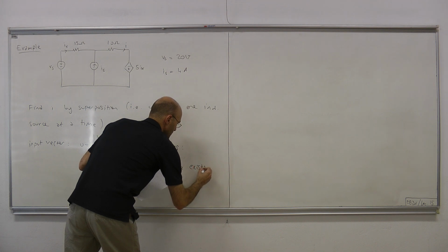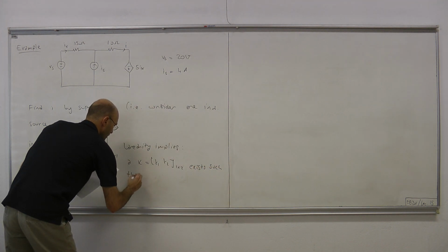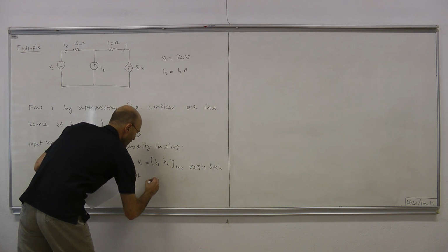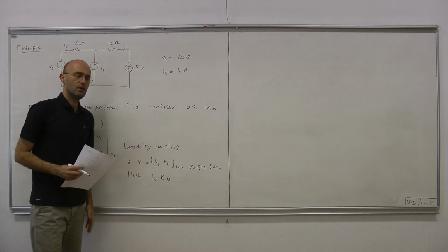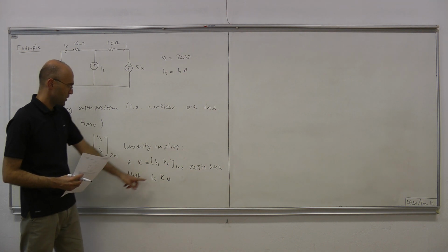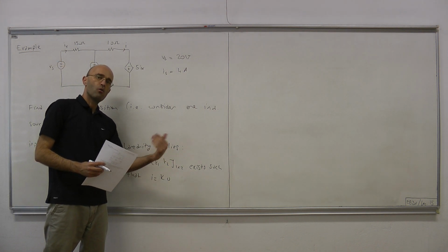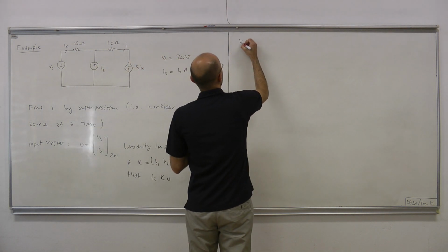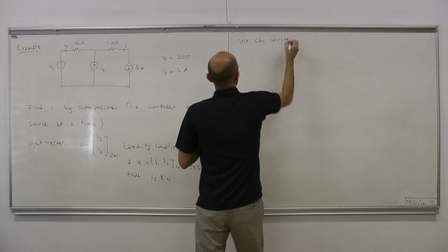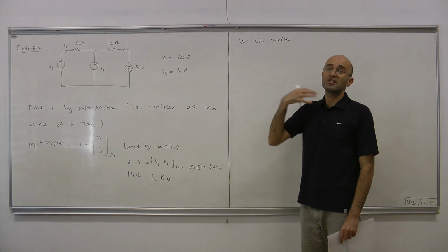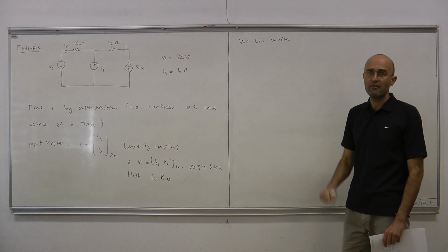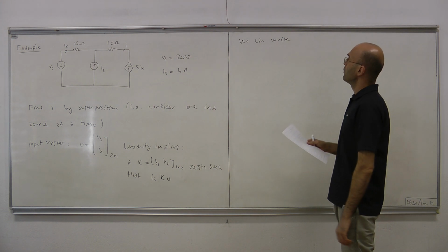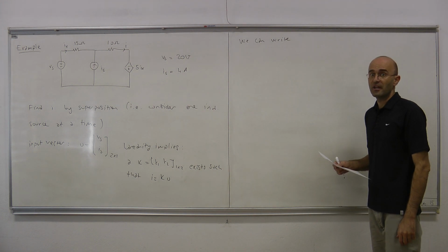It exists, and these K1 and K2 depend on the circuit topology and the parameters, of course, such that the output equals K times u. So K is 1 by 2, u is 2 by 1, therefore the product is 1 by 1, a scalar. And that scalar is our current, the output. Now, we don't know what K is, but we know that such a K exists. And that knowledge is itself valuable, even without knowing what K is. Because using that piece of information, we can generate the following reasoning, which is quite helpful.